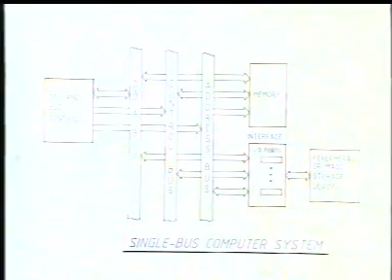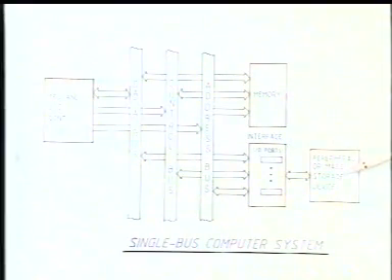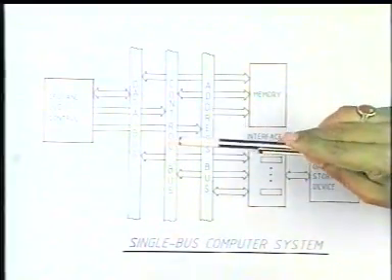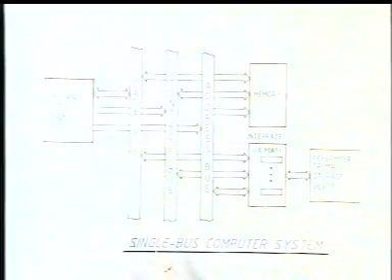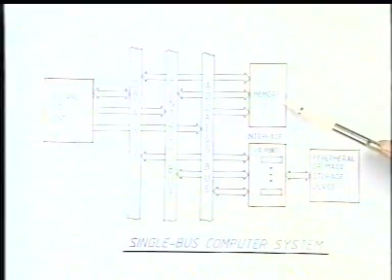Now, this is the central processing unit, which is communicating with the memory and the input-output devices, which are called the peripherals, and this is the interface unit or interface hardware, which communicates with the CPU and the memory. The memory and input-output devices are connected to the CPU through three independent buses. One is called the data bus, another is the address bus, and the third one is the control bus. You appreciate that the address bus is required because one has to give a unique address to the memory in order to access a particular data or parameter.